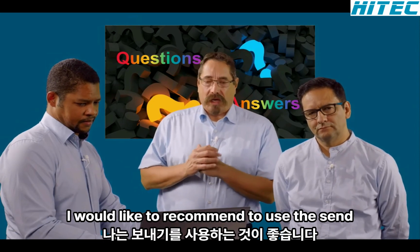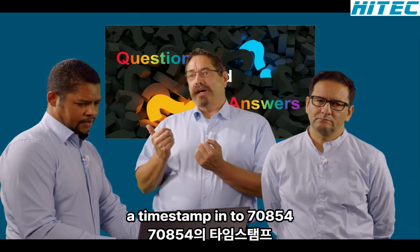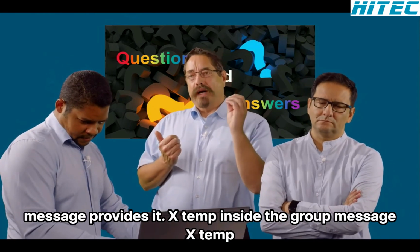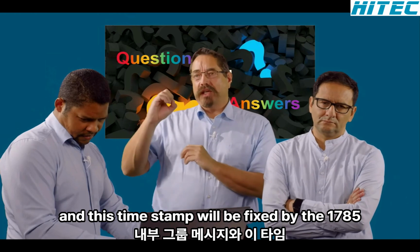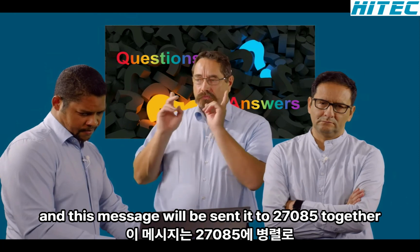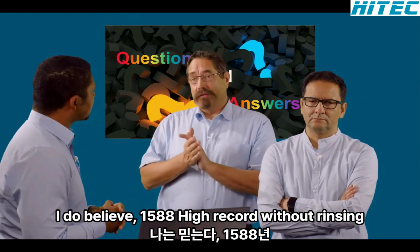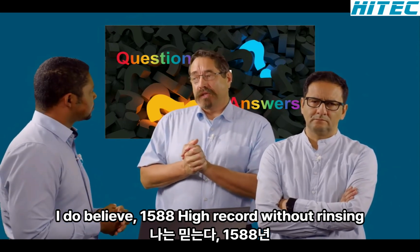With Goose, I would like to recommend using the sender timestamp in the 7K85 for the trigger line. In this case, the sender device, the publisher of the Goose message, provides its timestamp inside the Goose message. This timestamp will be fetched by the 7K85, and this will be the trigger line. This message will be sent to both 7K85 in parallel. Then we have a record, because all the equipment is PTP, IEEE 1588, high accuracy time synchronized, and we have very good fault records. Both are in sync.